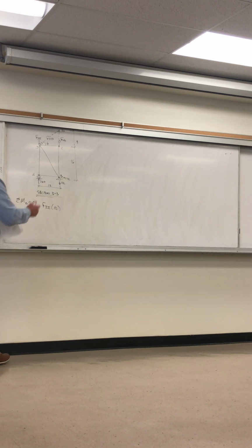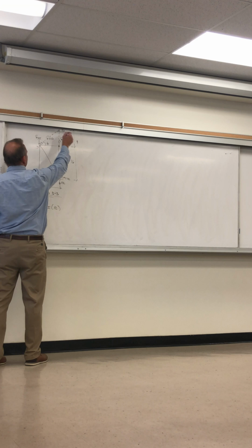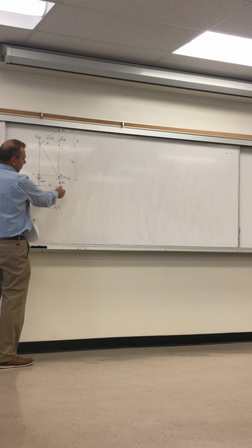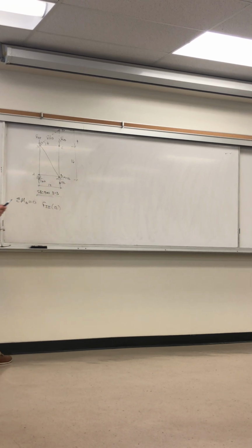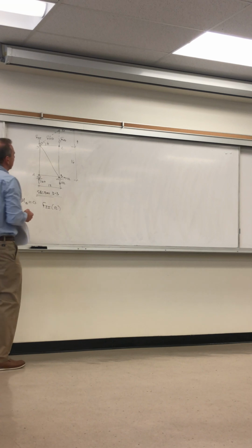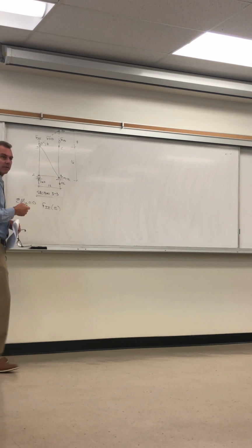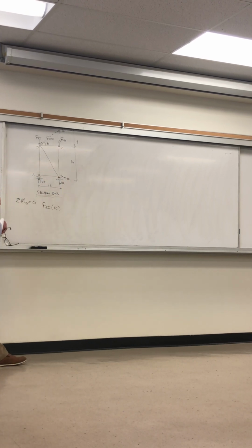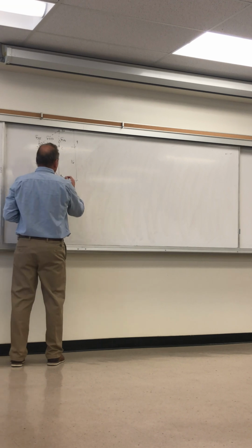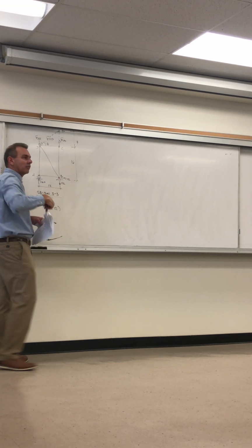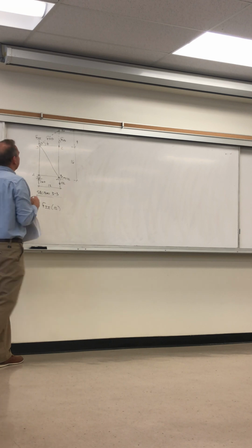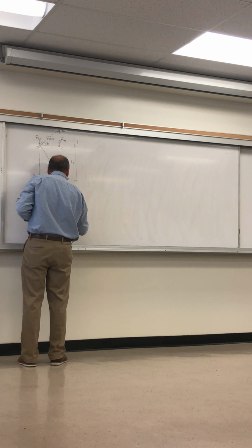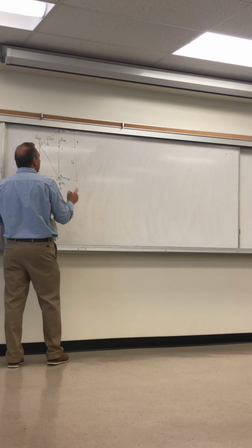And then I have this force times that distance counterclockwise along D. I don't have to include this 112, because its line of action goes right through D. But I do need to include the 12, the horizontal force. And 12 multiplied by the distance to the top, which is 16 plus 9, that's 25. So it's plus that force times the distance to D, that's also a counterclockwise moment, right? So this is plus 12 multiplied by 25.